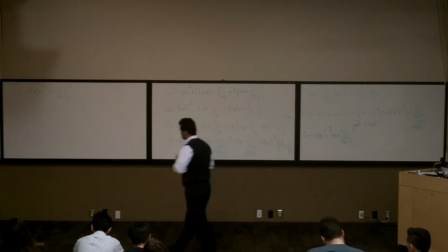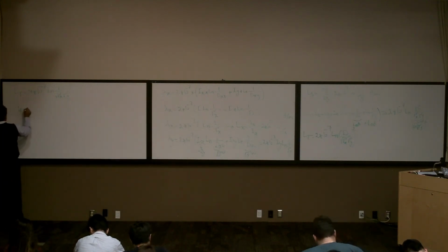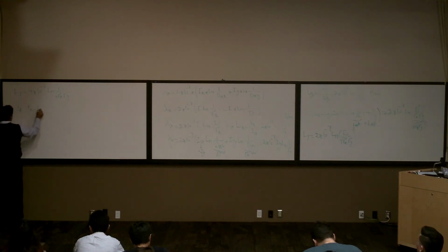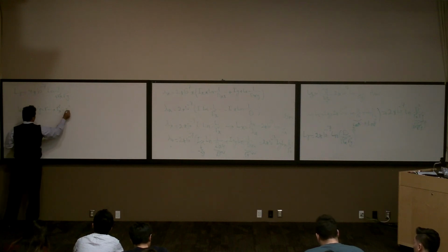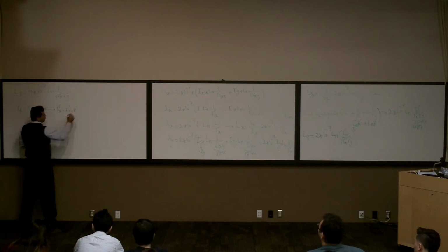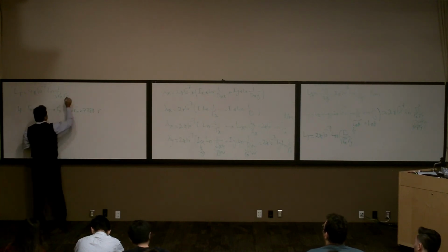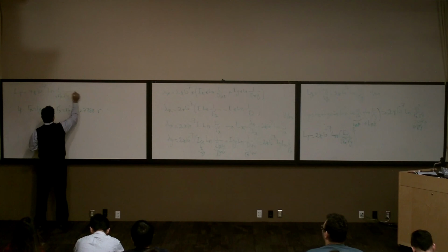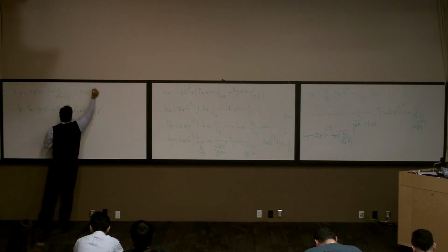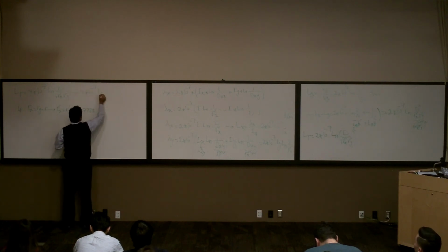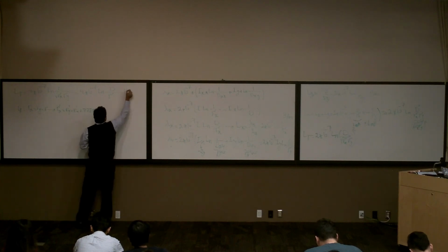So if Rx is equal to Ry equal to R, which means r prime x is equal to r prime y is equal to r prime, which is equal to 0.7788 r. So here this equation is going to be changing to 4 times 10 to the power of minus 7 ln of d over r prime, Henry.